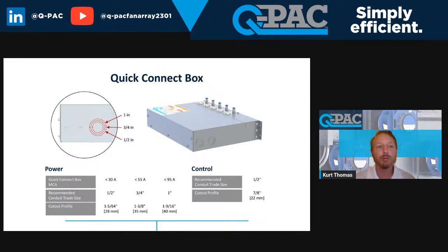It also greatly reduces the amount of work that electricians have to do, because instead of wiring each motor back to our control panel, they only actually have to do 2 runs, one for power and one for controls, all the way back to our external control panel. So that makes their life super easy, and they're not quoting the normal fee for installing 18 fans or however many they're doing.